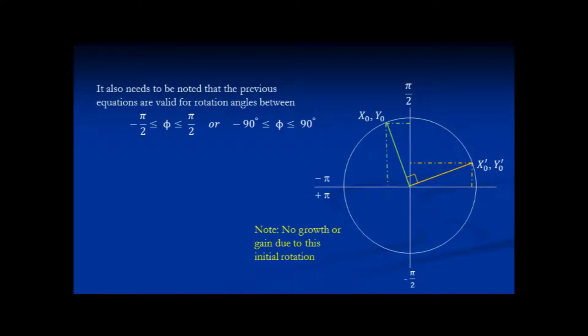There's one more item that we skipped over while discussing this algorithm. These CORDIC equations are limited to rotation angles from minus pi over 2 to plus pi over 2 due to the use of 2 to the 0 for the tangent of the first iteration. For composite rotation angles outside of this range, an additional rotation is required, which is done before using the CORDIC algorithm.